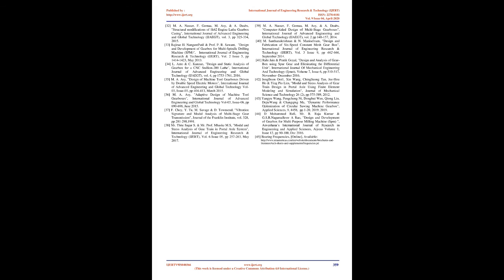Generally, the fourth modification has the highest natural frequency among all modifications, the widest range of natural frequencies, and the minimum value of deformation. Modification number 4 is the best stiff structure. So, the fourth modification is the versatile design against harmful vibration. Thus, the milling machine can safely use wide cutting conditions such as the cutting speed without dangerous resonance occurrence. These results prove that the given computerized nomograms and calculators written in VB6 are accurate, faster, reliable and expandable design tools.